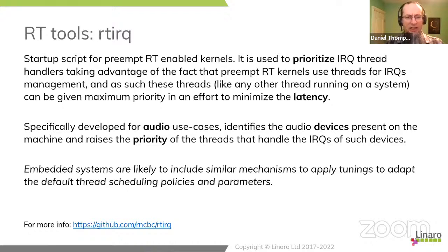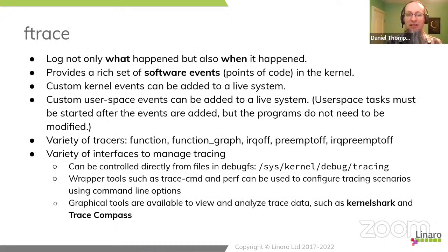So like I say, RT-IRQ is not going to be the shell script that you need to tune your system. It's not auto-tune. It is just there for a specific use case, and you will not have it in your kernel. But if you determine that you need to tune your system to improve its performance, you've benchmarked certain properties of, say, interrupt latencies, and discovered that interrupts are a bit too lumpy for a particular real-time thread, so you've got to manipulate things and move them around. This is what it's here for. So you'll have a service that is semantically equivalent, but it won't be based on that shell script. That's just an example of a tuning script that you run.